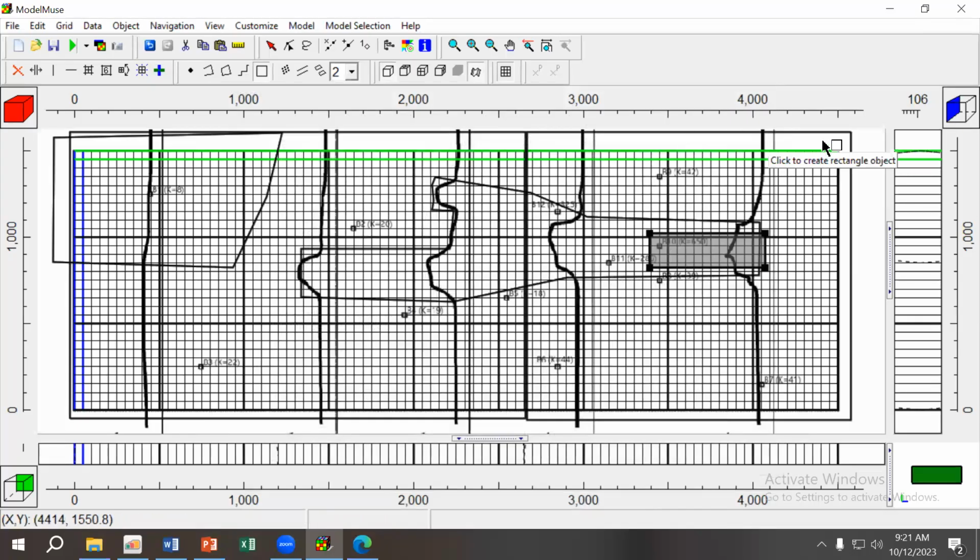And then finally I need to define this high hydraulic conductivity region near the river. To do this, I could come here, for example, and create another polygon here. It should, of course, be connected to these channels here, because otherwise, if this is not connected, this area is not going to be connected to the river.